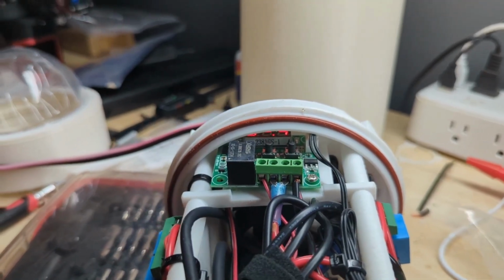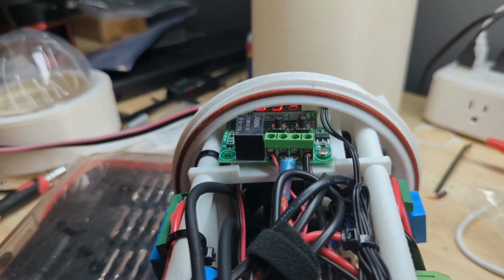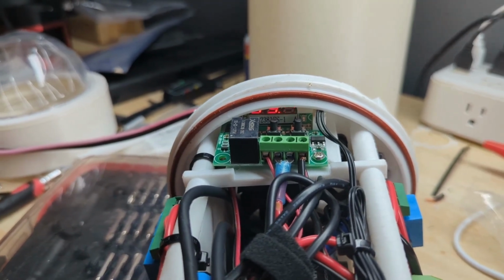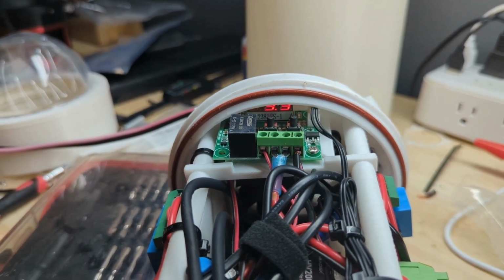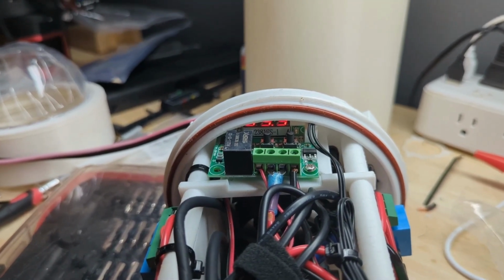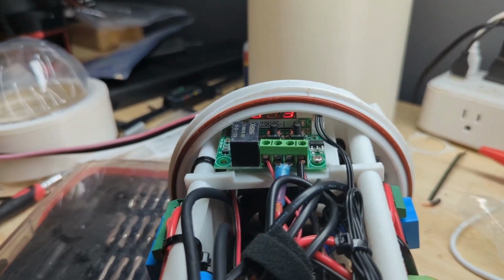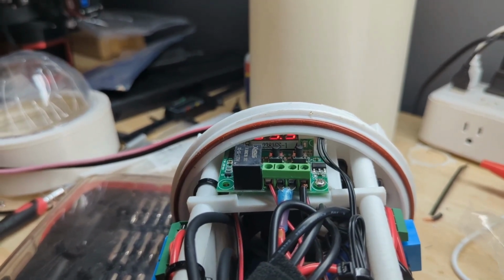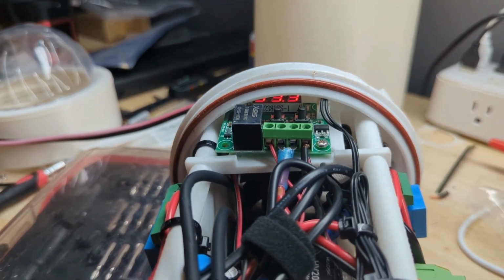The documentation on this device is not great. I kind of fumbled through it trying to figure out what the different settings were, but finally got around to understanding that's what it was. The 2 degree threshold is the default on there, and that can be adjusted. You can go to a different programming mode where you can say, I want it to be a 5 degree swing. So my threshold's 95, don't turn on until it hits 100 degrees, or the equivalent in Celsius.